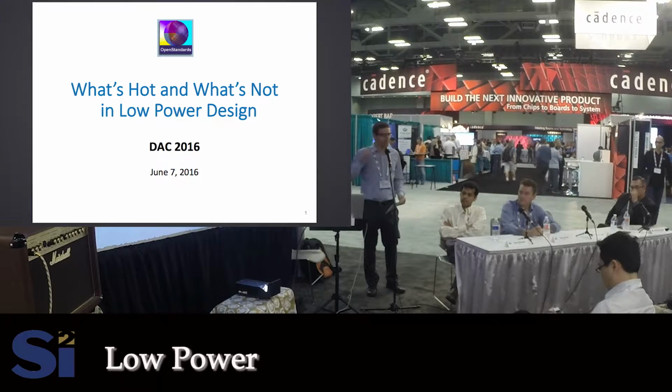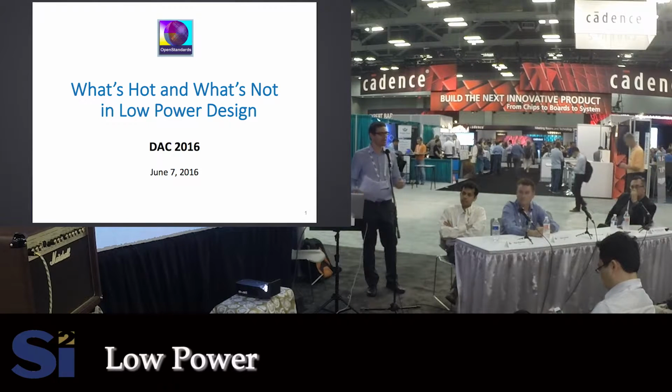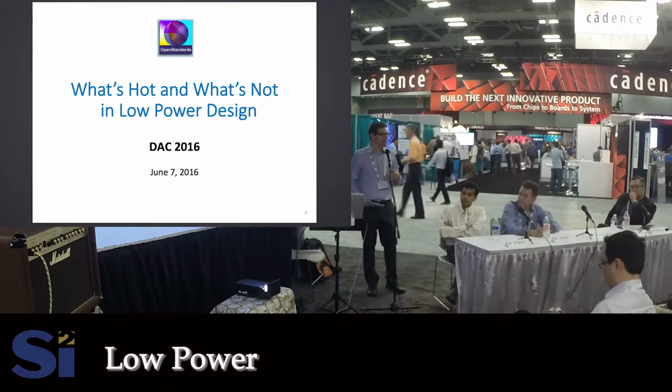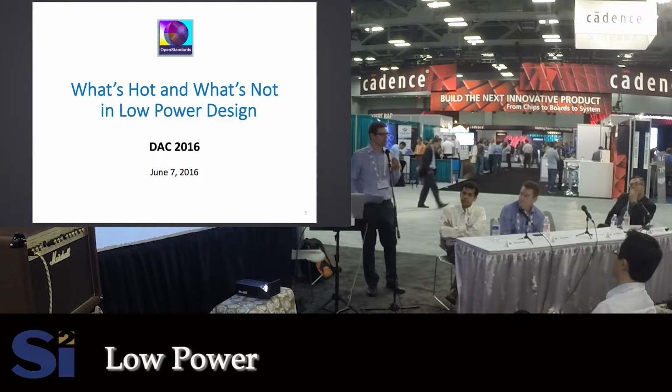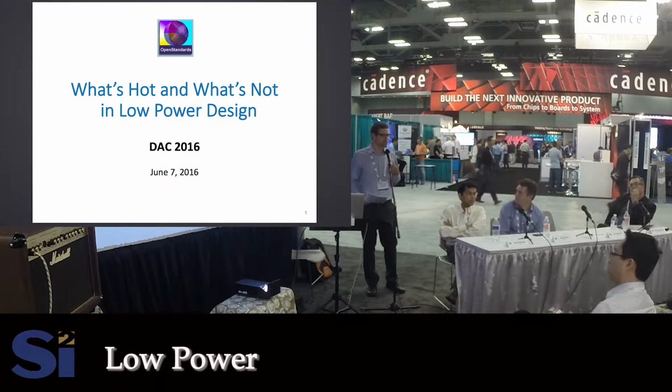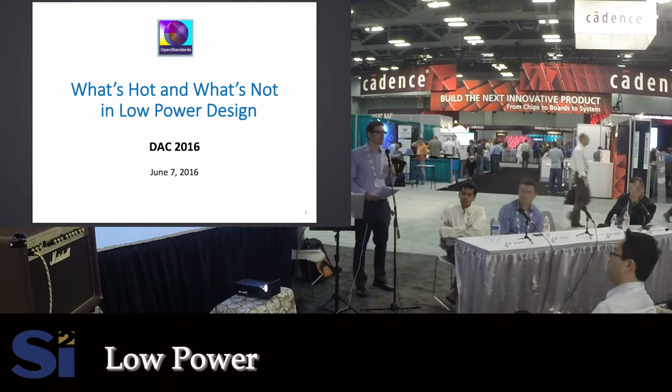And every block had a different timing recipe. Maybe you group paths, or maybe you ungroup some hierarchy. Fast forward to now, the industry has solved that problem, the EDA vendors, the library providers, etc. Most blocks today, timing closure is not a challenge because you swap in lower VT cells and timing's met. So we're not putting in as much effort.